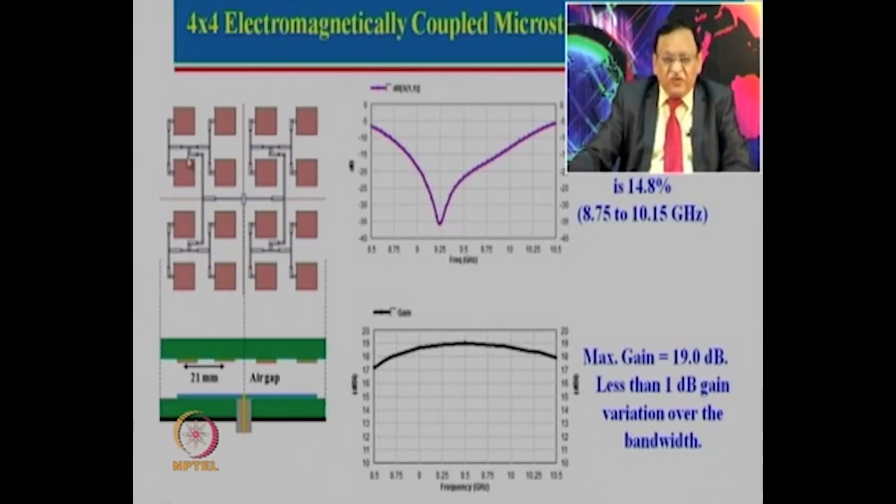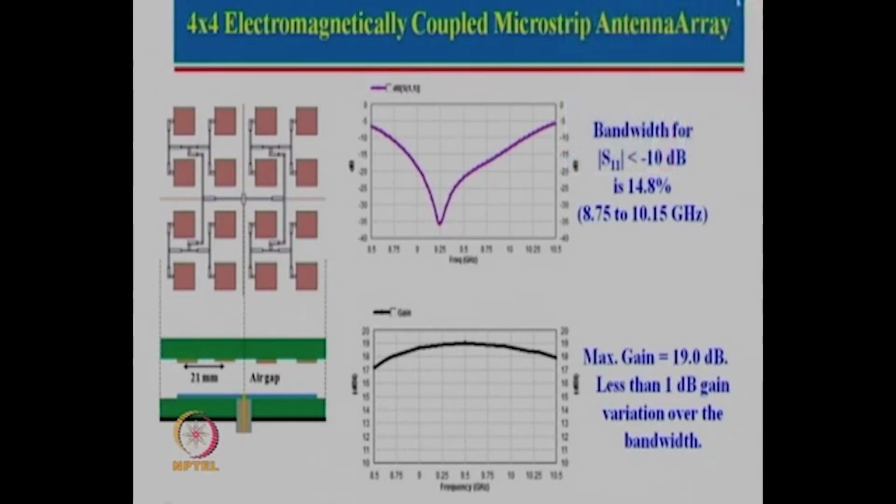Now we are connecting these feed networks like this here. For this also we have connected like this, and then we are connecting the feed point and feeding at this particular point. So you can think of this as my input, the power is getting divided into 2 ports here, then this one is further divided into 2 way, then this is divided into 2 way, then this is further divided into 2 way. That is how a 2 by 2 array is built up one by one. Because it is electromagnetically coupled, these 2 patches excite each other, which results in a very broad band antenna.